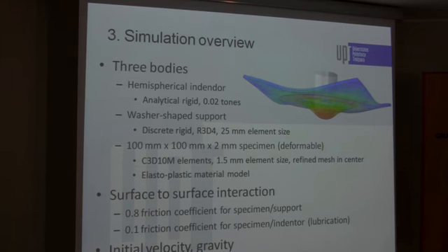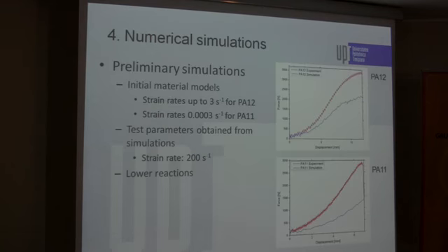And also, as a condition, we have the initial velocity, and we place the indenter a millimeter above the specimen. We use Galileo's law to calculate the initial speed for it to reach the desired speed at impact, and we also used gravity as a general model.